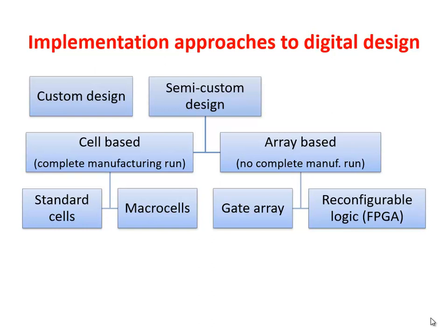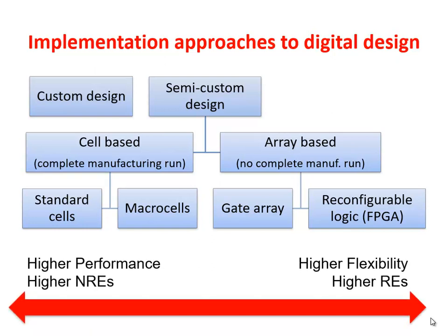So, from standard cells down to FPGA cells, we call these four options semi-custom design. And of course, there are different degrees of flexibility and performance, in the sense that you have the higher flexibility with the reconfigurable logic, completely programmable, because you can change whatever you want every time with software.